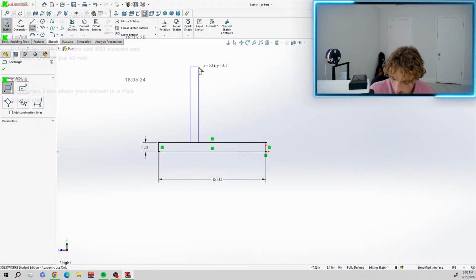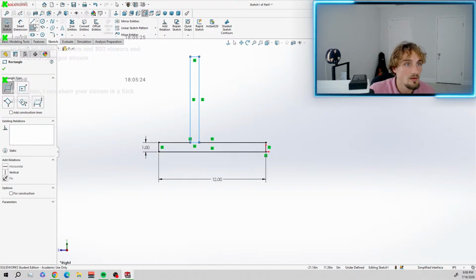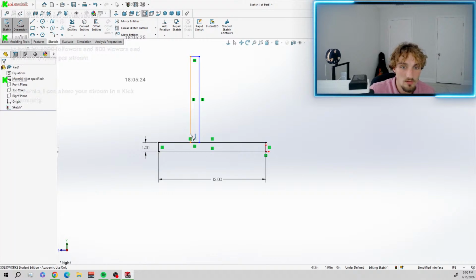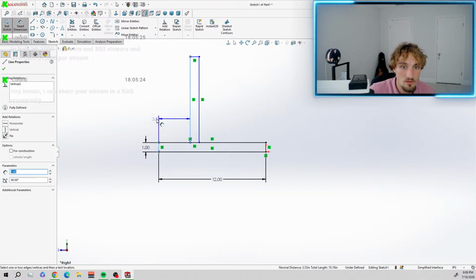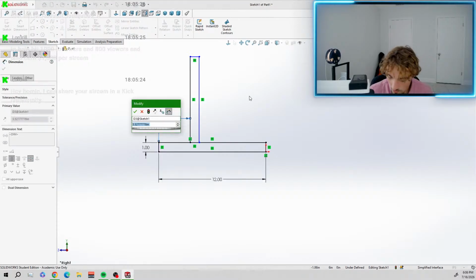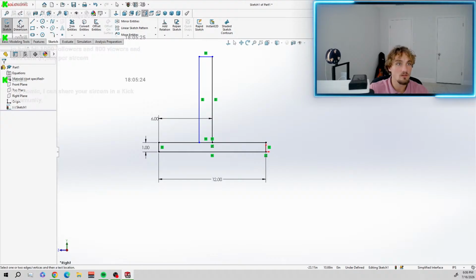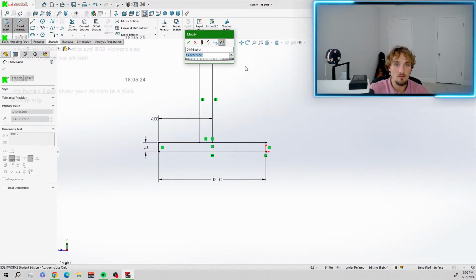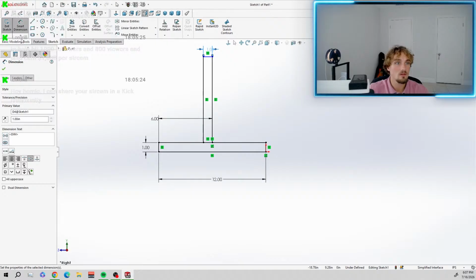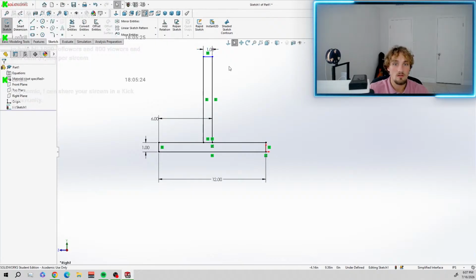Like this. Now how high is it going to be? So first of all, I want to do this and I want to go, let's think about this. What's the offset? Probably do it just halfway, right? Let's just go halfway, so 6. We'll leave that room. Okay, 6. Check. Smart dimensions. Bang. Okay, 1 inch. Check. Okay, just like that.